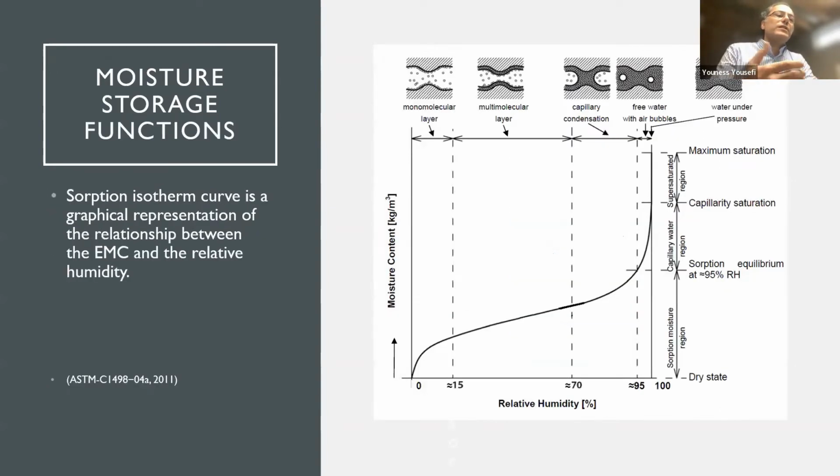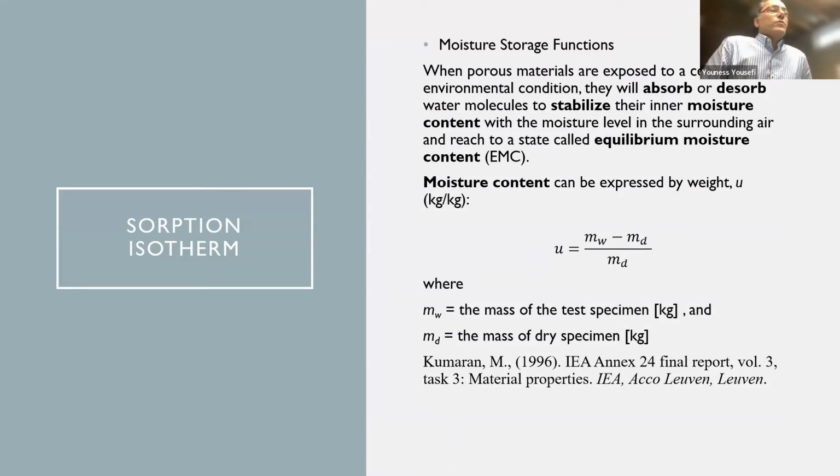So when we measure this amount of vapor concentrated as moisture in the material pores, and plot it against the relative humidity, we call it the absorption isotherm. So we can have the absorption isotherm of the material at a certain temperature. Then we calculated these properties by subtracting the dry weight of the material from the moist material weight.